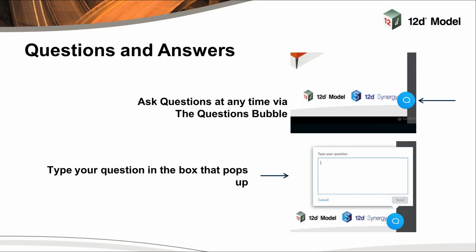Can leaders be created on cross sections similar to the way in which dimensions can be created? Not leaders as such. If you're doing leaders for a typical cross section, you could have those leaders in another model that is placed over the top. Some people plot the typical cross section to a model to start off with, arrange all of the additional information they want in that model, and then use that in a plan frame or add that data to the cross section. So not within the MPS itself, you can't insert those leaders.